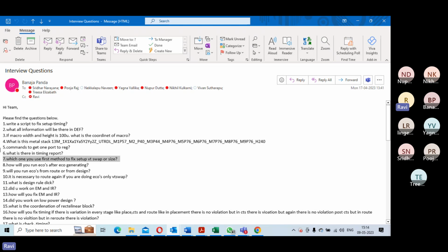But sometimes the cell library could have a flaw, and if it has actually swapped something, then you can check. Ideally there should not be any change, but you can run verify DRC. If it is exactly the same as before, no shorts, no opens, or the same numbers, then you don't have to reroute. But if there are some changes because of some library issues between the VT types, then you may have to do some incremental touch-ups to your route.